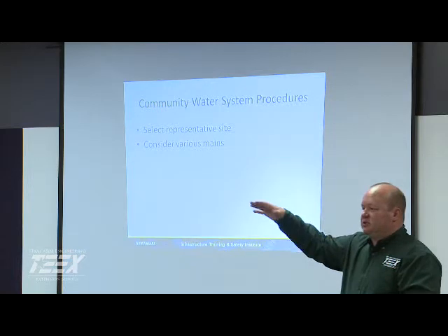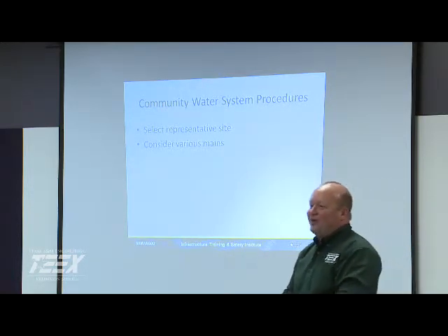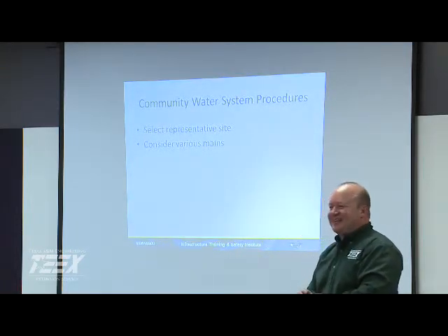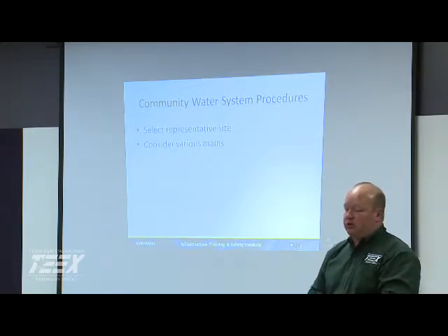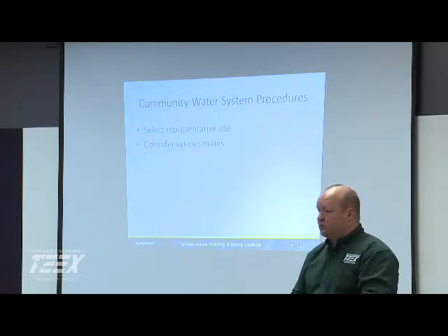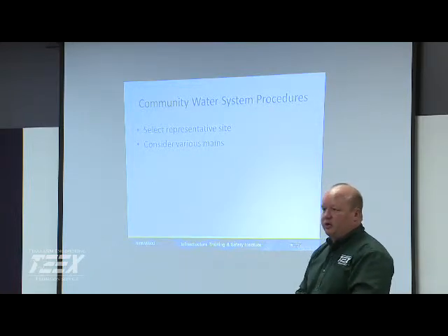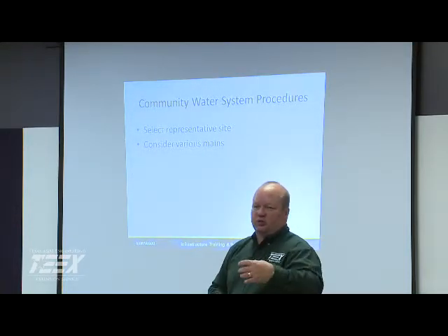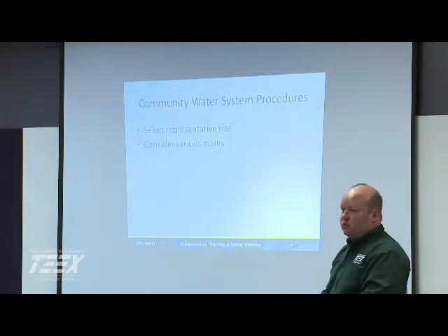So, we had 60-inch valves at the ASR facility, and after me out there turning a bunch of them a couple of times, I started looking online for hydraulic valve turners. You have to be careful with them, of course. You've got to know how to operate them properly, but they're very beneficial, especially if it's truck mounted. Pull up, throw your key on there, and it'll figure out what direction it's supposed to go. They work under real low pressures that increase as they're operating them. So it can be very beneficial as part of the PM program.